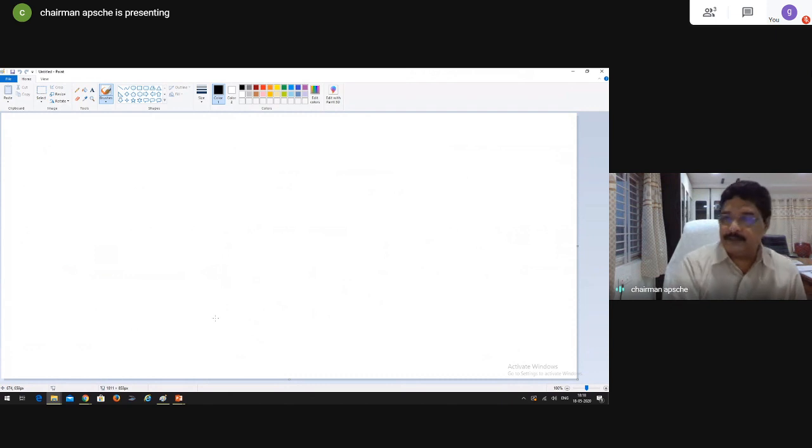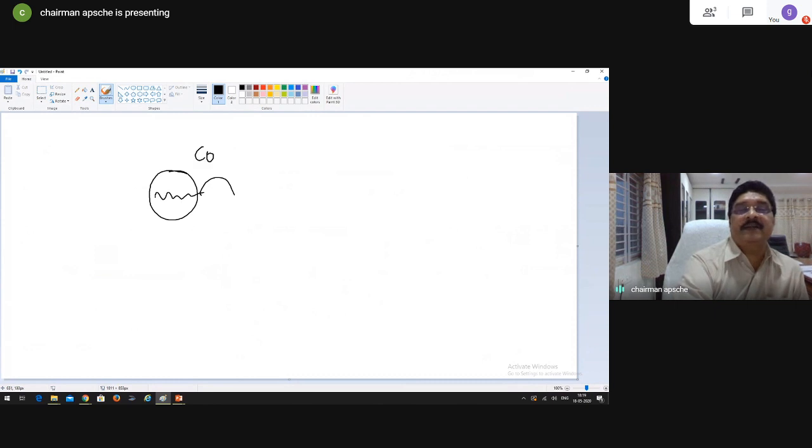See, I'll give you one final explanation as quickly as I can. We discussed transient heat conduction, particularly lumped heat capacity, the lumped systems. In a lumped system, the whole body is at one temperature. We compare the resistance to heat transfer inside the solid, by conduction, with the convection heat transfer taking place outside the solid.